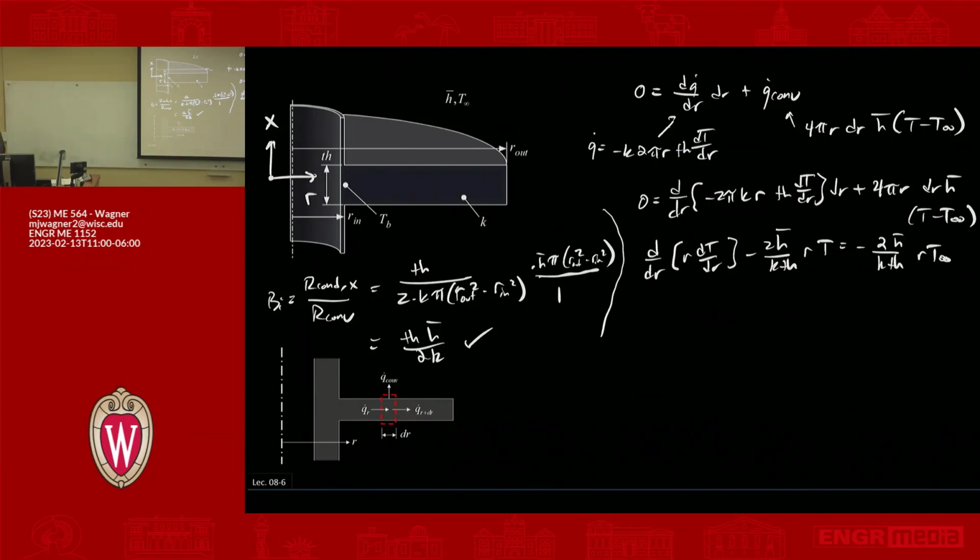In the future, though, there are situations where you might plug in some non-homogeneous ODE or PDE, and Maple just won't solve it. But if you were to break it up yourself and do a homogeneous solution and then a particular solution, it would solve it. So you might still have to use your own knowledge or judgment as you're going through the process just to get it to do what you want. Okay, but there's our ODE. Let's make that substitution where we say T is equal to T_H plus T_P.